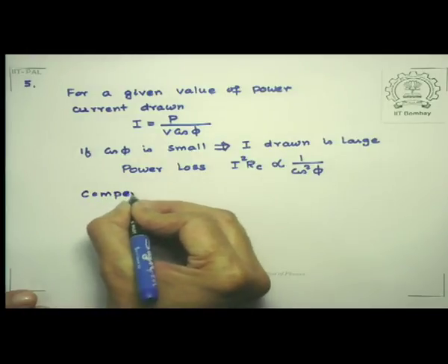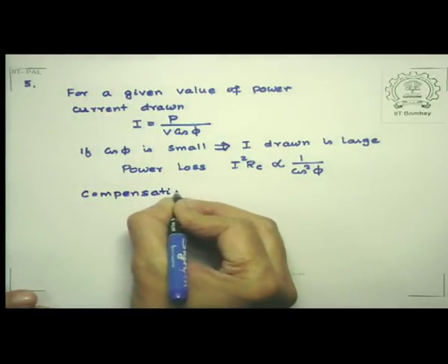And the reason why we are having this situation is that the apparent power is substantially different from the true power, and that arises because there are reactive elements in the circuit. So therefore, if we could somehow compensate the reactive elements, we will illustrate our ideas with a specific example, but let's first look at